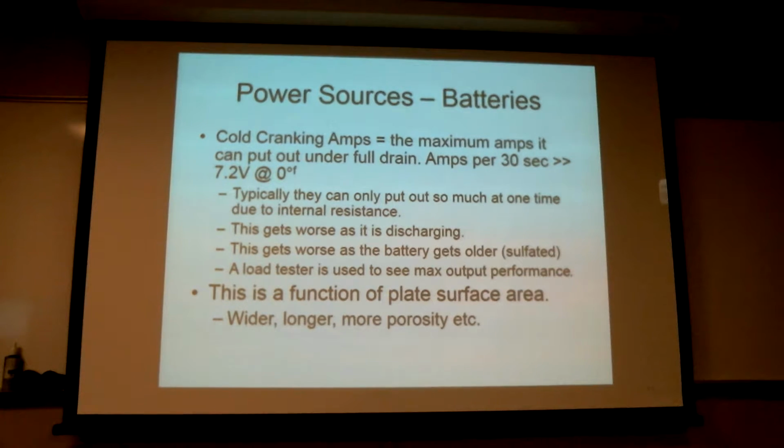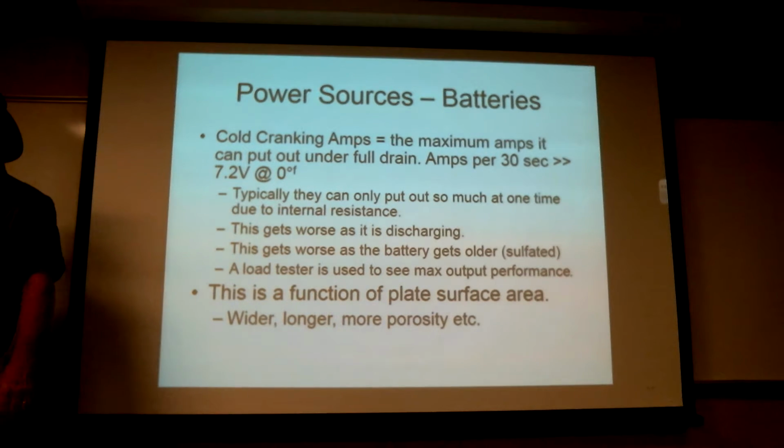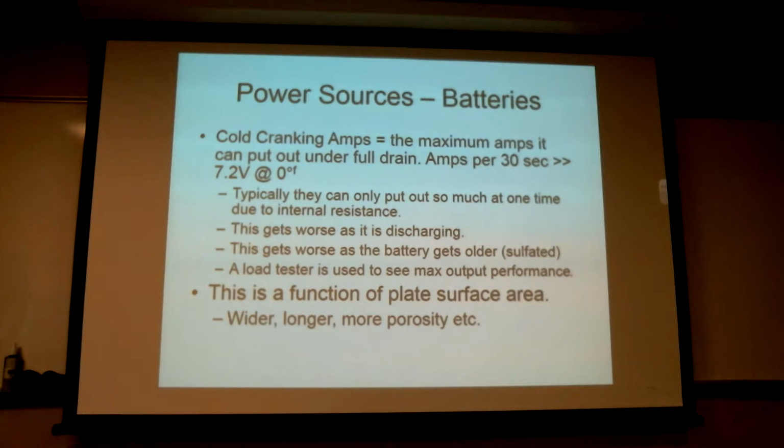Nowadays, since you can't get in there, you've just got what I've got, like the one I have, made by Blue Point, which is Snap-on's auxiliary company. It's just a handle with a big metal box. Two big cables come out with two big battery clamps. Clamp on positive, negative. It's got a voltmeter and a big switch. And inside the metal box, it's just a big toaster element. After about 10 seconds, it gets bright red. And you've got the little meter going. That places the load on it, right? Yeah, it's just like hitting it with a starter. Big resistor. Yeah, it's just a big toaster element, right?